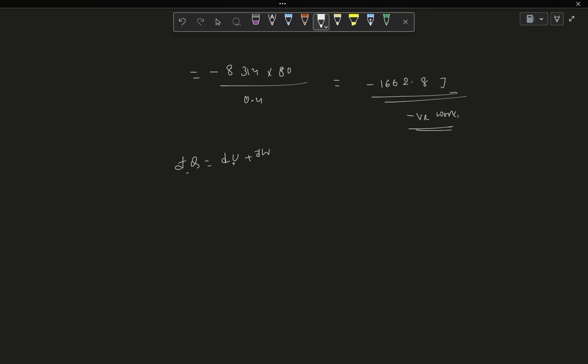And by that we mean that when the system is doing work, its internal energy will get reduced, so your du becomes negative, and that is when you call the dw positive, because du equals minus dw. So if du is negative, dw is positive, and that means the system is doing work by itself, or this is work done by the system, right?